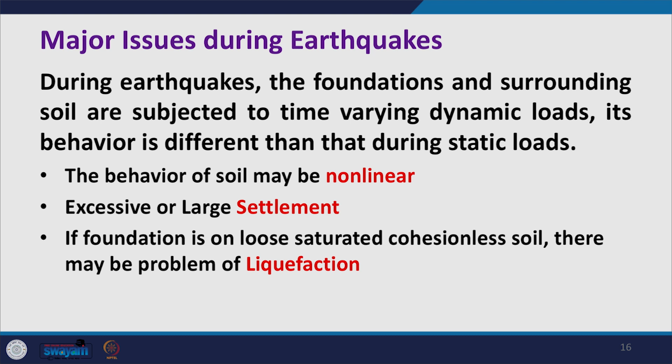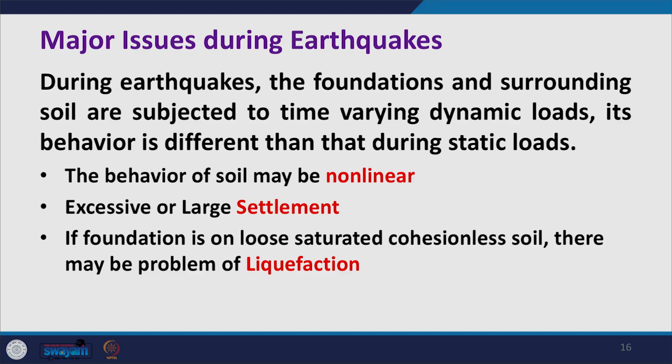First of all, during an earthquake, particularly when there is strong shaking, the behavior of soil is normally nonlinear. So, that means we need to consider the nonlinear properties of the soil in the analysis. Then there could be excessive large settlement, particularly if your soil is liquefiable, then settlements are very excessive.